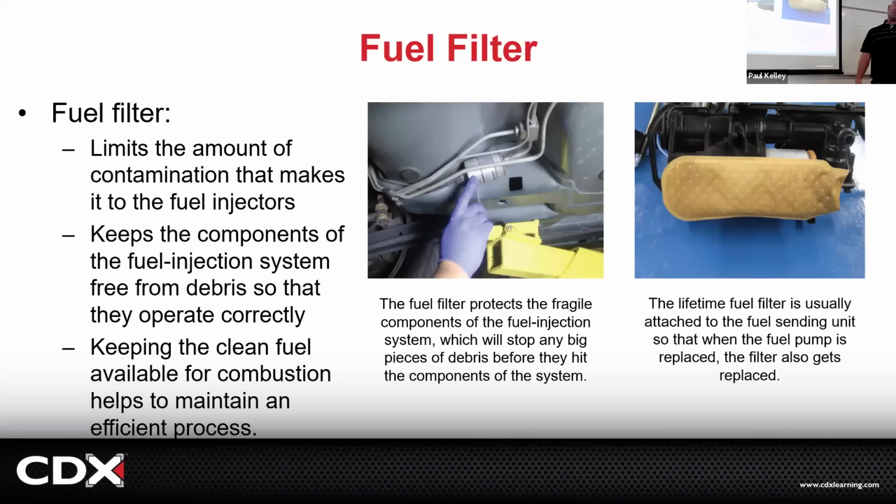Oh, definitely. That was just back in the day. This is what we were doing. These were kind of junk. And the thing is, if this fuel filter was clogged up, it would give us the fuel starvation. If this fuel filter was clogged up and you didn't change it, it would put excess strain on the pump and it could cause your pump to fail prematurely. So if you were to roll into O'Reilly's, they'd be like, oh, you need a fuel pump? You really should get the filter. And you're like, why? They'd be like, oh, the filter causes the pump to wear out. And that could be true. And then you change the filter and be like, oh, now it's quiet. No, it's true. Those are fun times.